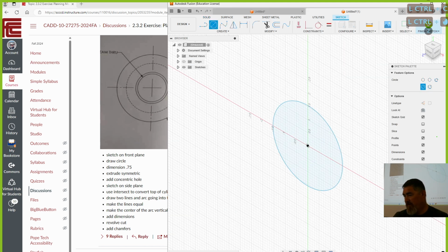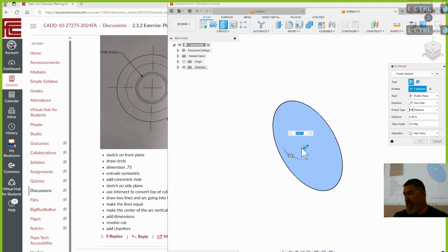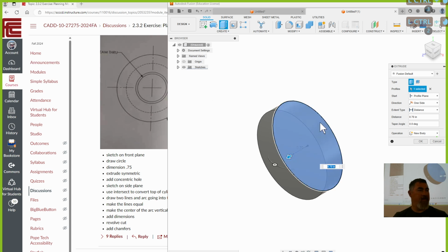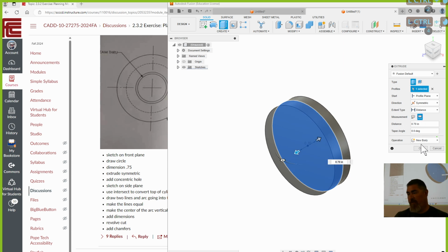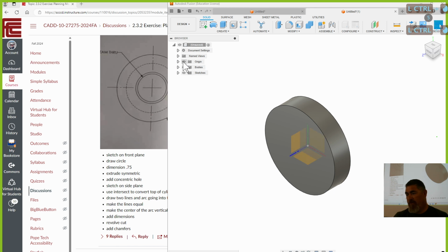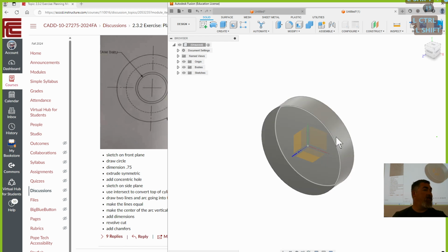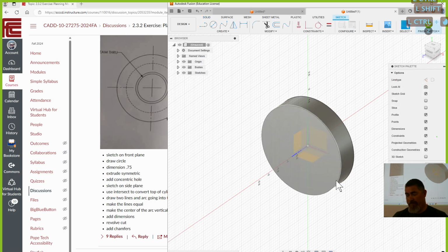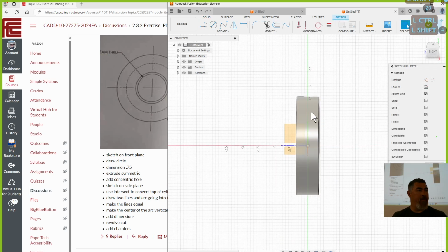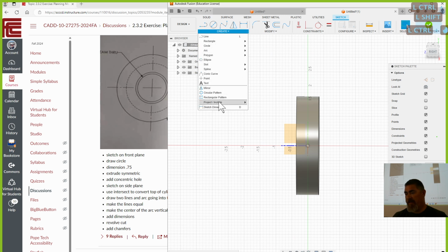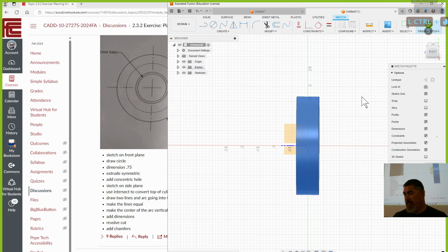So when I do that circle and then extrude it, if I do it this way, my origin is on the back side. If I tell it to be symmetric, and I can tell it the overall length, now I'm going to keep my origin right there in the middle of it. So now I can sketch back on that if I need to for something, or if I need to mirror, or I want to line something up with that. Because I want to keep my cut centered. When I create a sketch there, that point's there for me, so I can do my intersection, or my include.